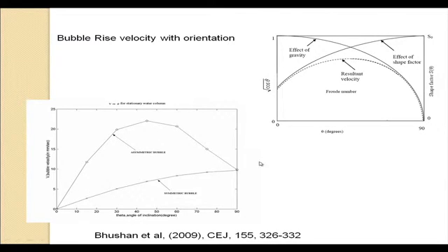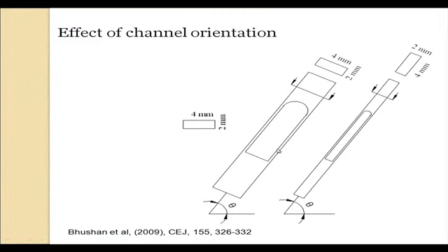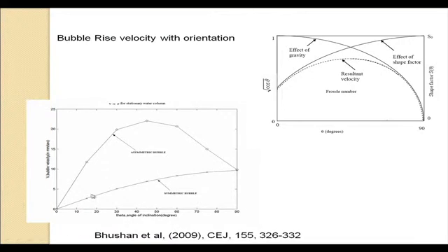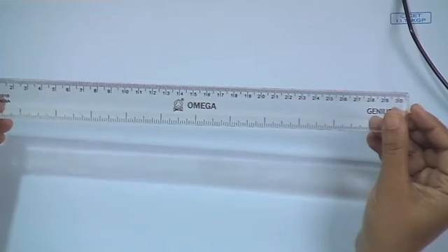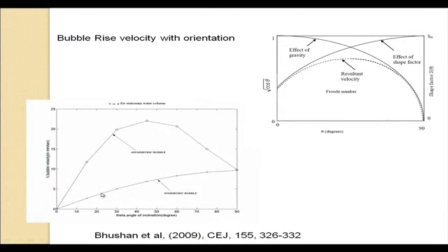Well, to come back to our discussion, for the first orientation, which is the orientation shown here, the bubble rise velocity exhibits the same type of curve as is expected. But if the Taylor bubble is held in this other way and made to rise in this fashion, we find firstly that the rise velocity is always less than in the other orientation. Secondly, the velocity rises steadily from the horizontal to the vertical orientation, and the rate of rise is faster initially and then gradually becomes much slower.